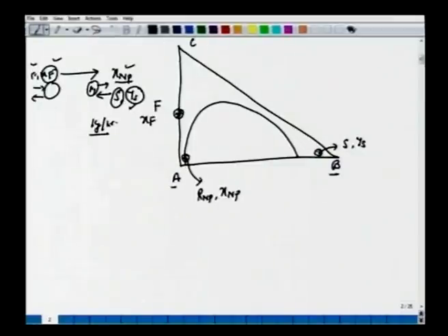All right. So now if we connect F and S, then we can have somewhere here the mixing coordinate M. So let's say that we have some coordinate M. Okay. So this represents the combination or mixing of F and S. And now since we know the raffinate coordinate here, we can connect this to obtain this E1. So this would be E1.